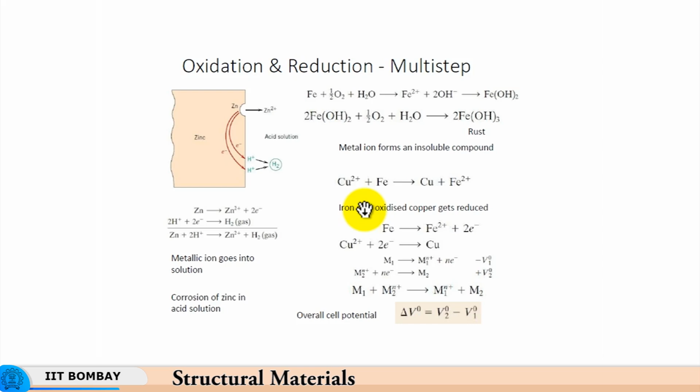Now, there can be various reasons why this can form. For instance, we were talking about stress corrosion. Let us say zinc in this region is highly stressed. When you make a product designed in such a way that there is a sharp change in the cross section, you will have a region where the stress is very high, a region of stress discontinuity.